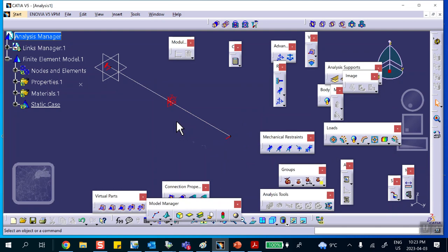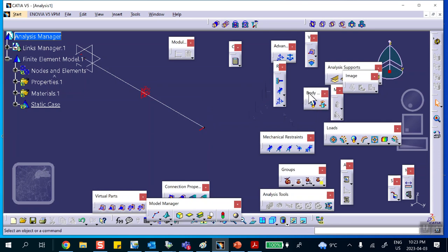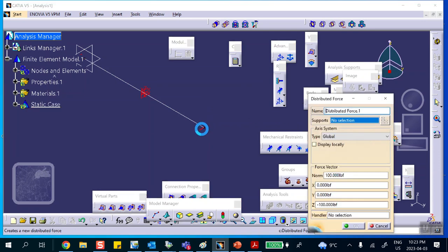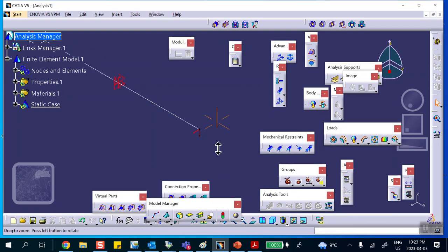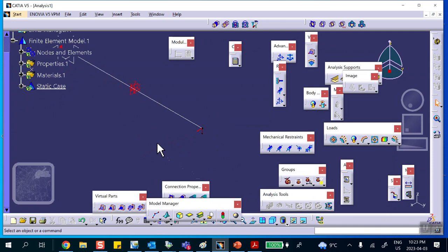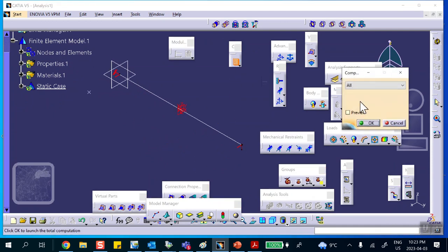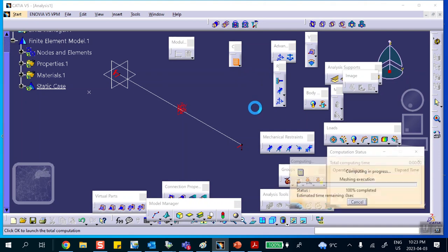Okay, good. Now, we're going to apply a load here. This is a static load right now, so we're going to apply a static load of 100 pounds downward at this location. You can see that it's right here. This is the load that we applied. There's nothing fancy. If I just run this, it's going to bend down. This is an obvious static problem.